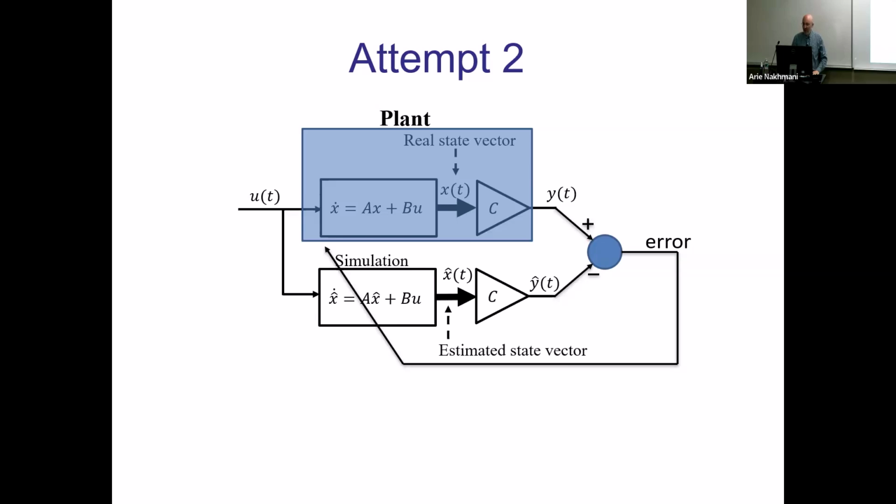All of that is the observer. Everything else is observed. The part with the error measurer, and including the error simulation, the measure, including everything, this is the observer. You're taking just U and Y, putting them into the observer as two inputs, and the output is X. This is how it works.